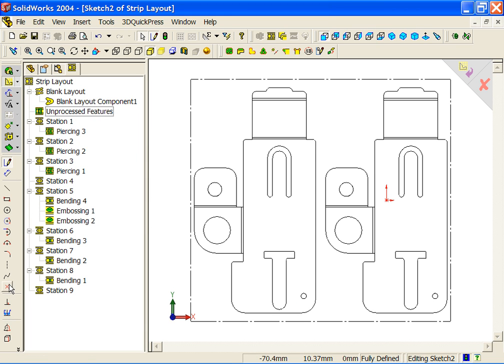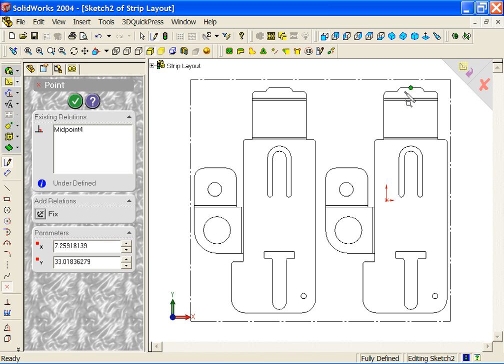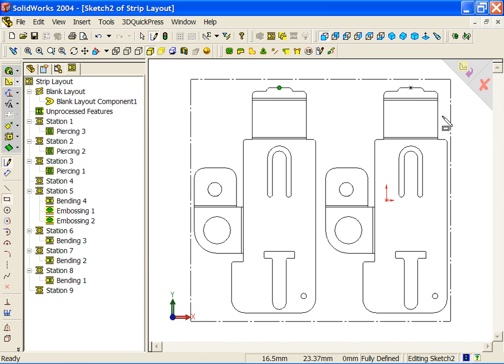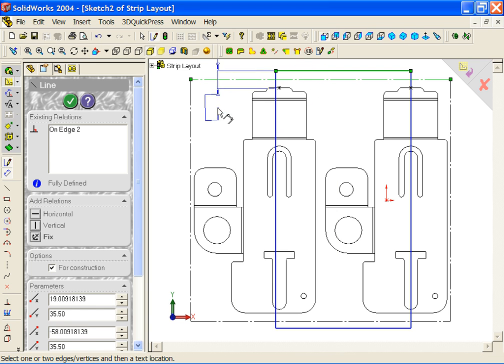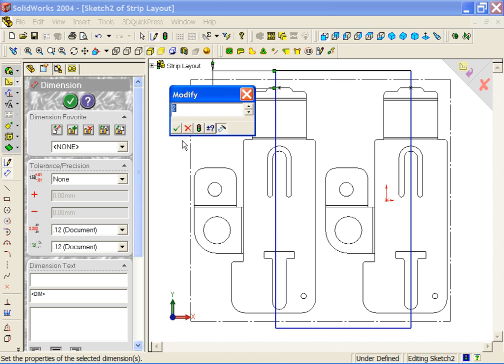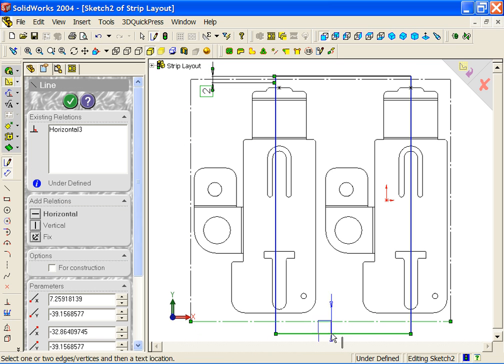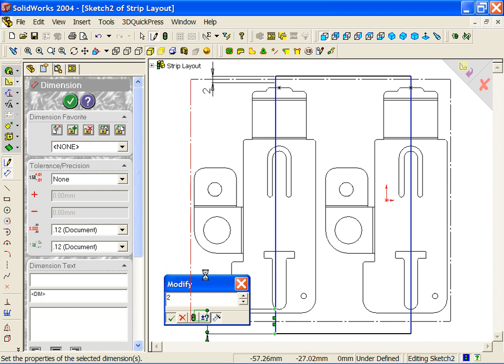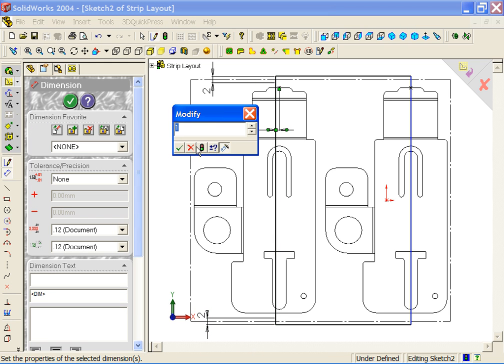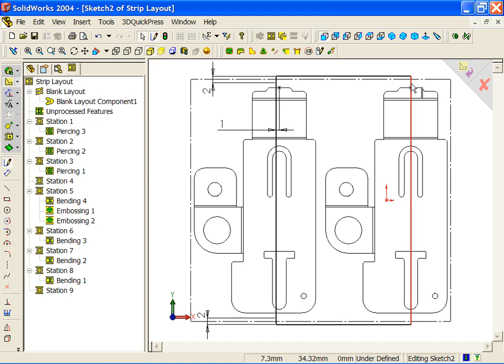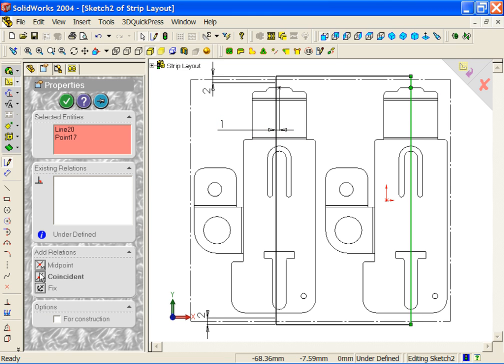and utilize SolidWorks sketch tools such as point tools, arcs, lines, splines, whatever tools you need. You're utilizing the standard SolidWorks toolkit. Put some smart dimensions on. Let's say we want an offset material of 2 always, and we want an offset from the bottom of the same. We'd like an offset for some undercut of 1, and finally let's make sure that these two are always the same.